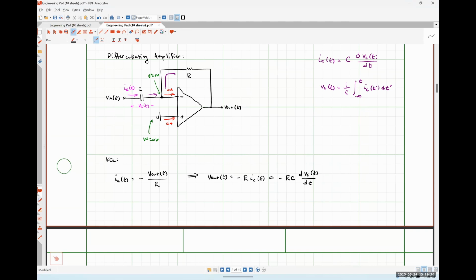Somebody who didn't take me for circuits 1 and therefore doesn't already know the answer, tell me: how are VC and VN related? They are the same, yeah. VN is a shorthand notation for a voltage source where the positive polarity terminal of VN is applied at that node and the negative polarity terminal of VN is at ground.